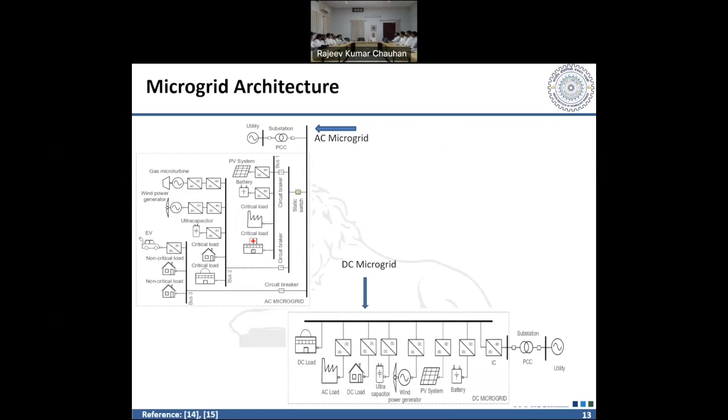So what we are doing, we are connecting the AC, converting into the DC. DC, again we are using the inverter, converting into the AC. So what was happening before? You are directly driving the compressor with the AC. When the temperature is reached, it will cut down, and then again it will start. So as you know, in starting, it will draw a very large current. It is consuming a lot of power.